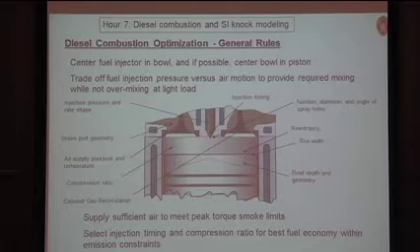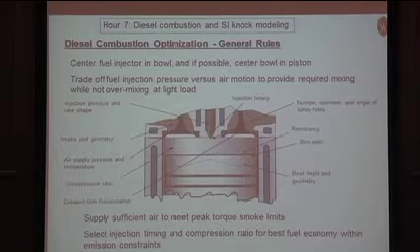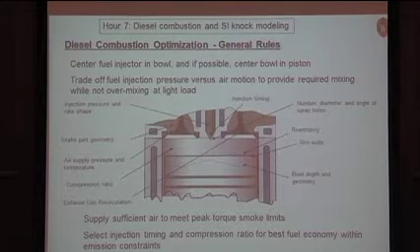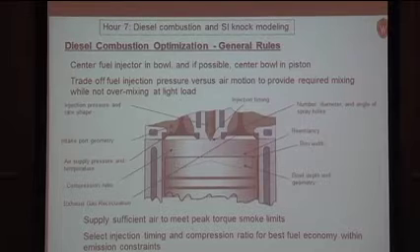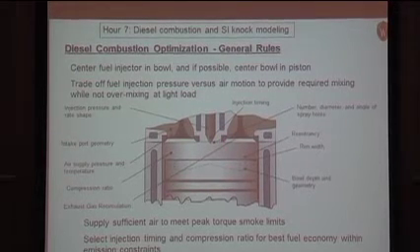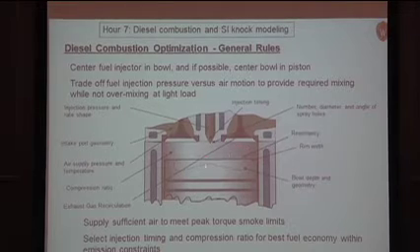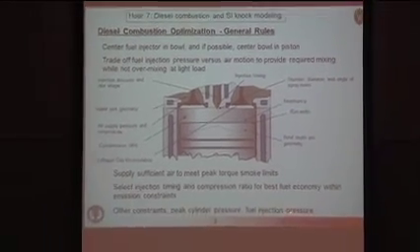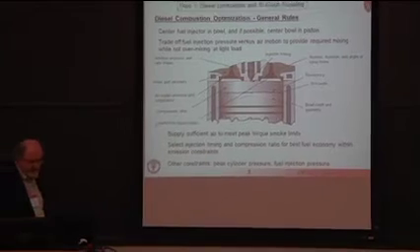So a lot of design parameters for optimal design of diesel engines. And when all is said and done, there are several constraints. For example, you cannot exceed a certain peak pressure in the engine, otherwise it'll blow apart. You also have to worry about limits on the fuel injection pressure.